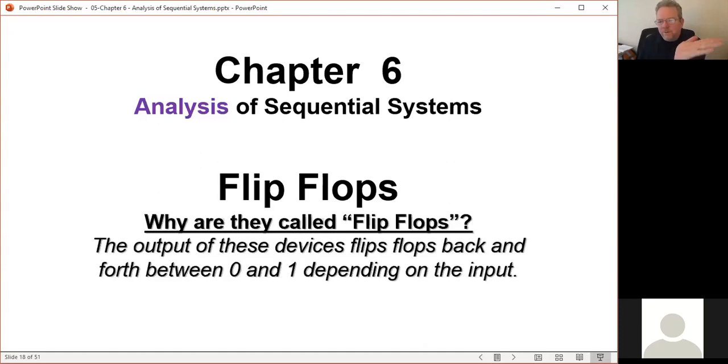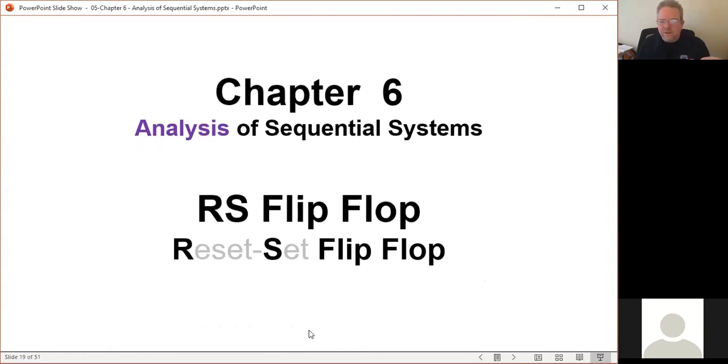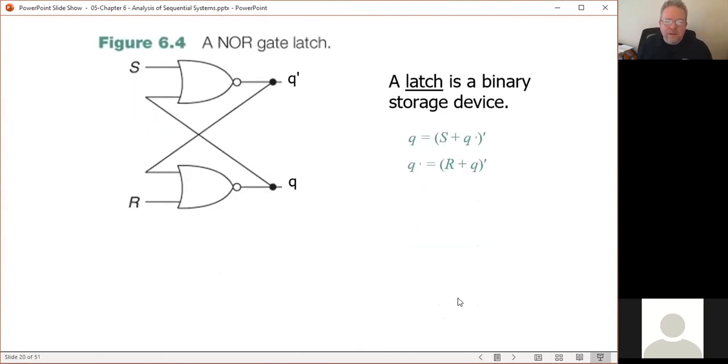That flipping of 0 to 1, as a memory element remembering either a 1 or a 0, is controlled with two inputs. And that's really the R and the S. So the R stands for reset, in which you're basically saying with the R, you turn it on and then the output goes to 0. So you're resetting it back to 0. And the S input is a set and it basically turns it to 1. So that's the fundamental part of it.